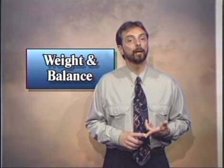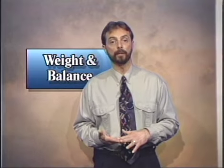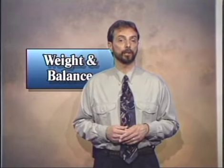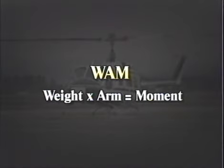You'll need to be able to calculate whether the weight and center of gravity are within limits, the location of the CG, and how adding a passenger or how fuel burn will affect the center of gravity. Weight times arm equals moment. Use this formula to compute both the left and right moments.